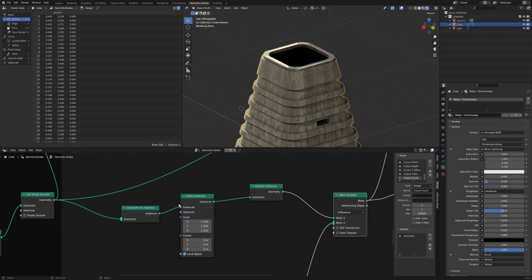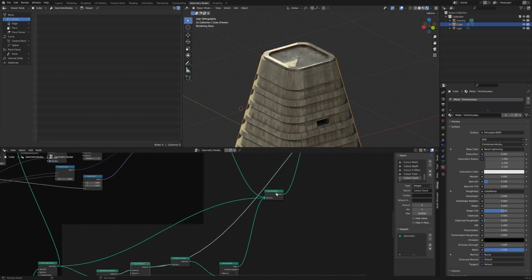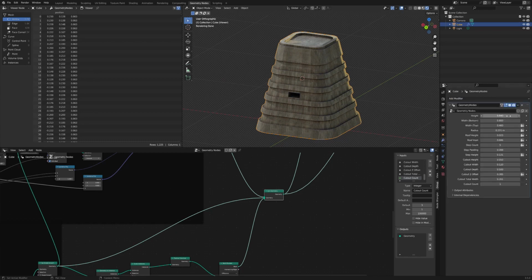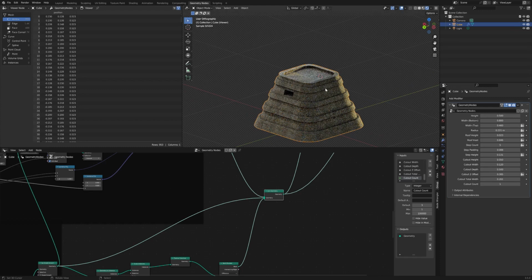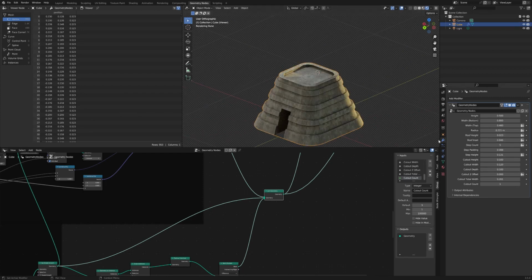The little trick we can do is where we had our scale instances earlier that was taking the base shape and expanding it out to then do our booleans. If you change the z to be like 0.99999, it still treats it as 1, but it does mean you don't have exact overlap, and then you get to see the output. So now if we change our geometry from our geometry nodes, height 0.5 for example, we can change our cutout height. Let's go a cutout height of 0.25, and then z offset of 0, and cutout height of 0.5, something like that. Yeah, we're starting to now get the Dune-like buildings, which is working really nicely.